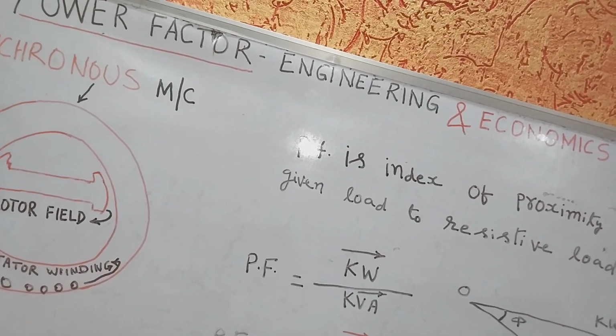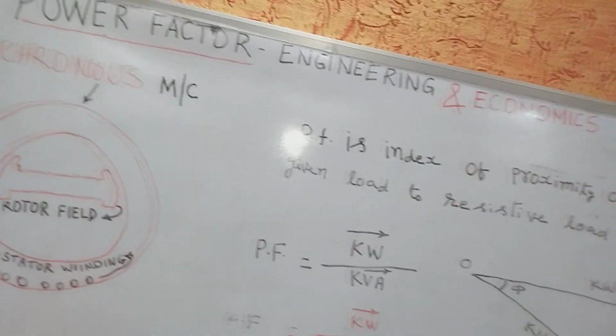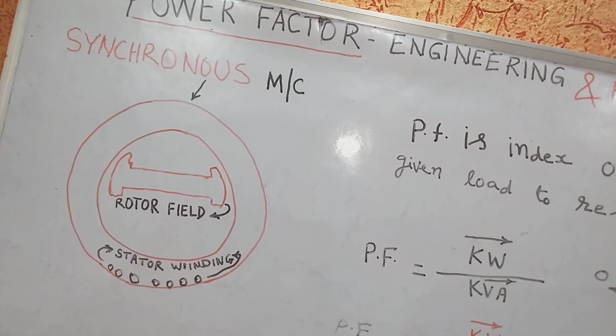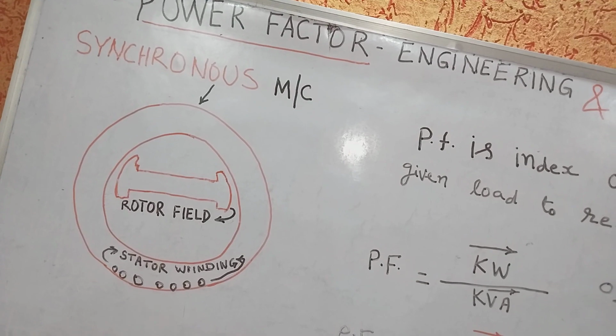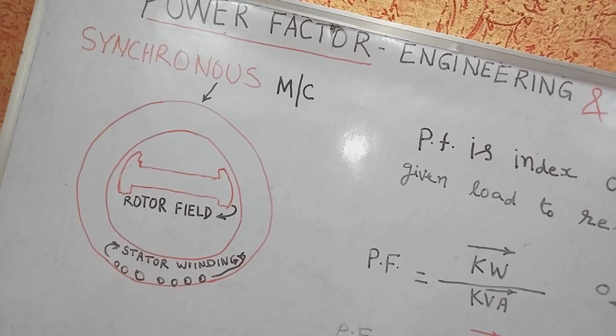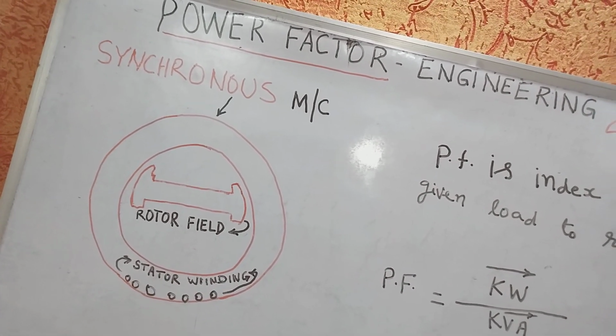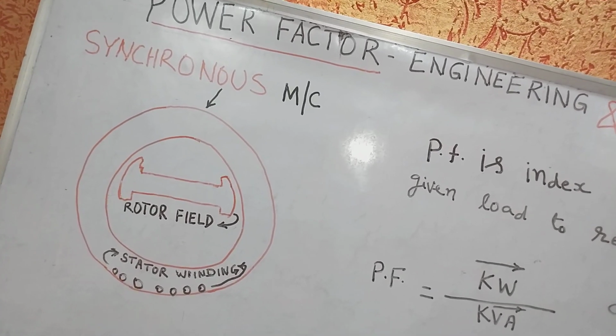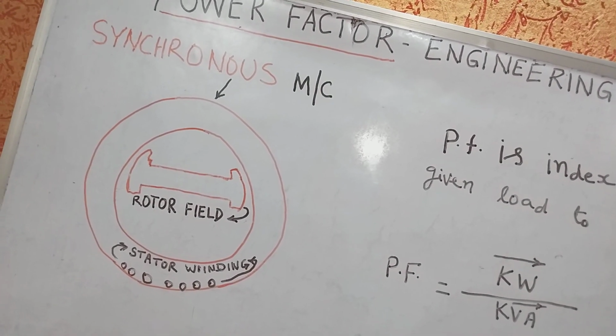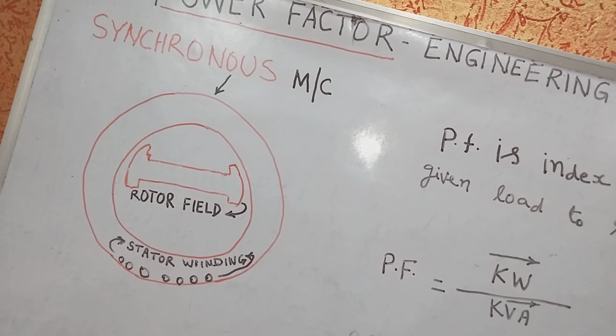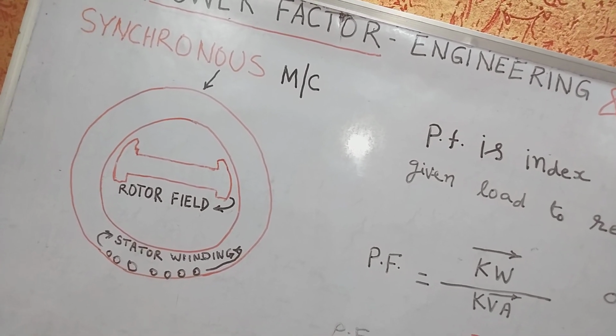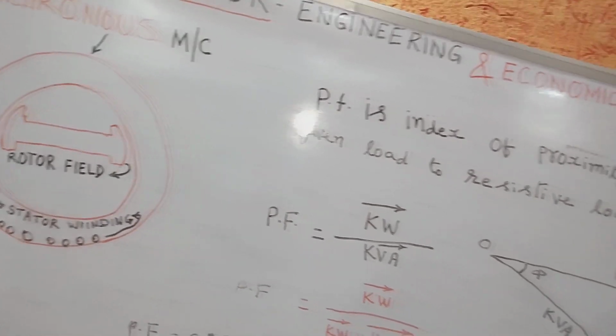In the first place, generators, transformers, conductors, etc. are rated in terms of kVA rather than kilowatts because their losses and heating are very nearly determined by voltage and current regardless of power factor.